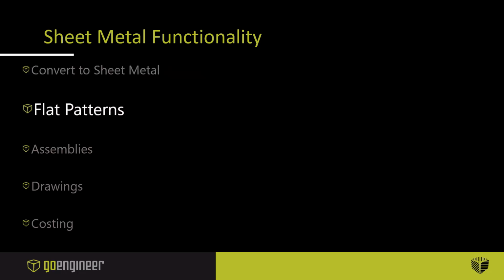Our next topic is going to be looking at the flat pattern. So imagine that fold and unfold feature just applied to the whole model. And that's what your machinist or whoever's doing your burn part is going to be interested in. How does the part need to be cut out from the stock material, and then of course the bends will be applied later. So we'll look at the flat orientation of our different parts here.